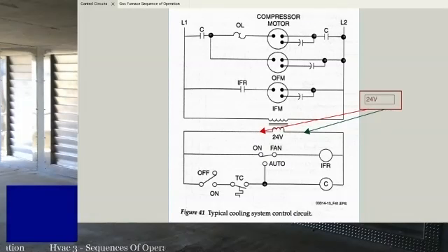You know what I mean? Does it stay right there at 24 volts the whole time? Because sometimes if you got a bad wire on the control side, you'll actually start at 24 and then drop down to like 13 or 12 or something like that if you got a bad common connection or a bad wire.